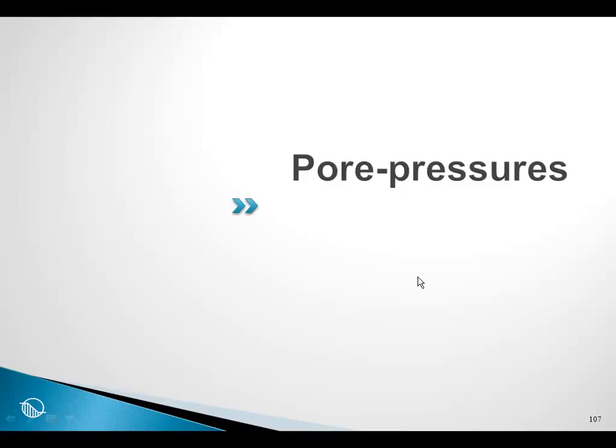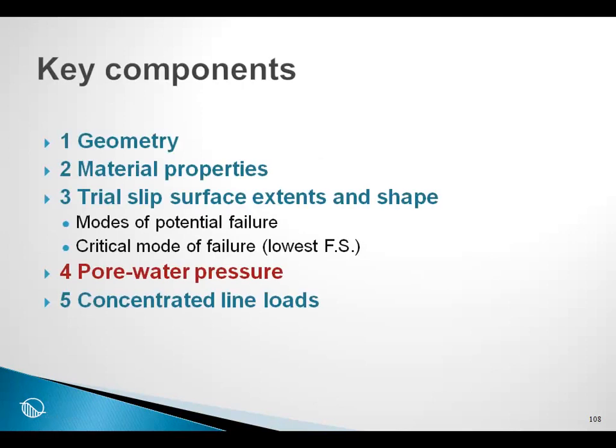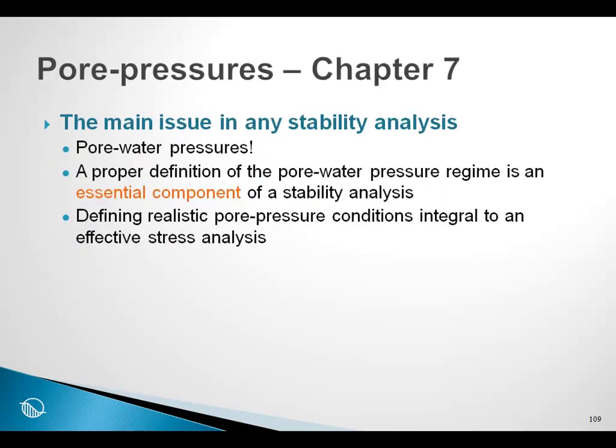This session is about defining pore water pressure conditions in Slope W. Once again, here is our key list of components, and certainly one of the very important aspects of any stability analysis is to define the pore water pressure conditions if we want to use effective strength parameters. Once again, we have an entire chapter on defining pore pressures in the Slope W engineering book.